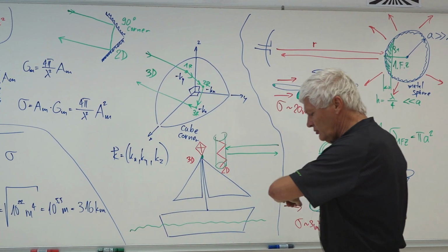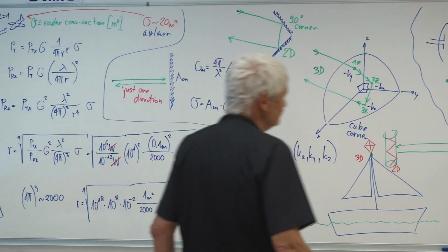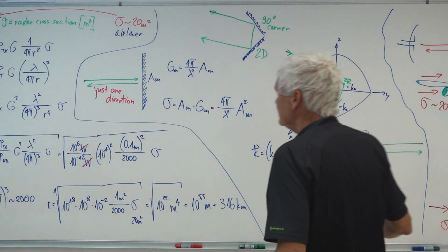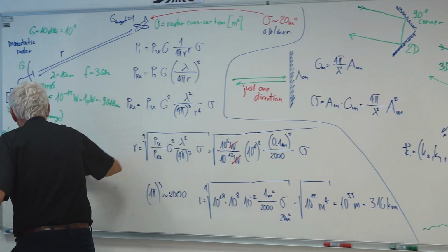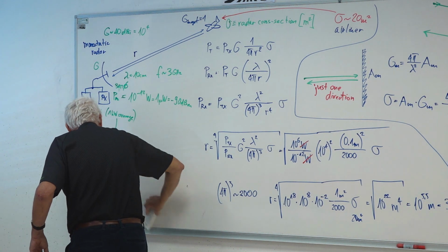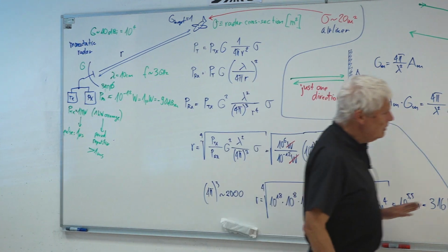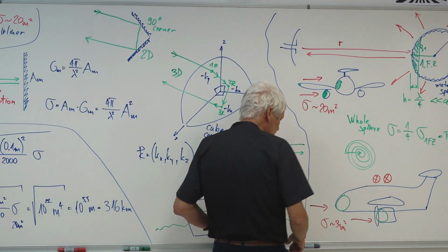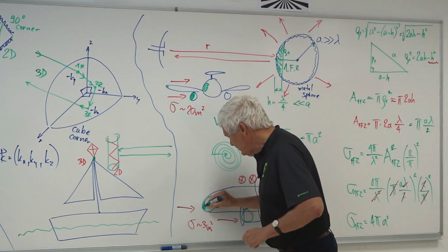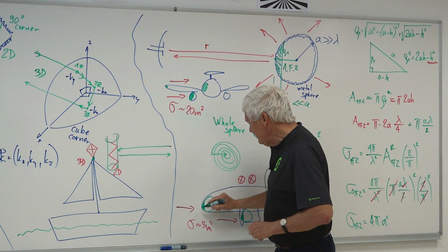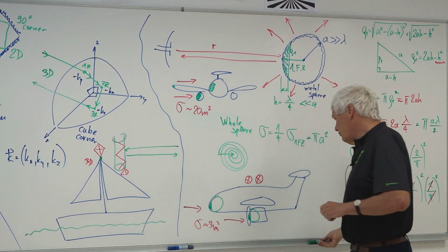Now the question is how to make an invisible aircraft. Where is the eraser? Here. How to make things invisible on the radar? The idea behind making things invisible is having no vertical flat surfaces, because this is actually the first Fresnel zone, here and here on the engine. Having no flat surfaces, this is not according to the aerodynamics requirements, but having no flat surfaces.